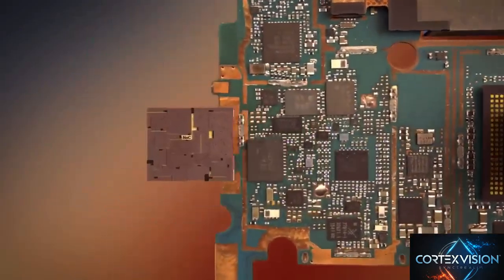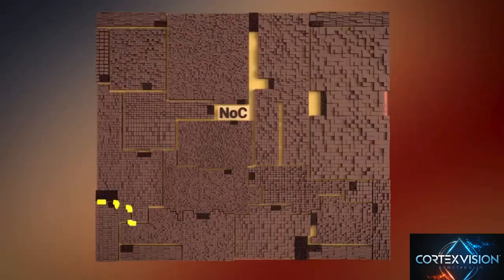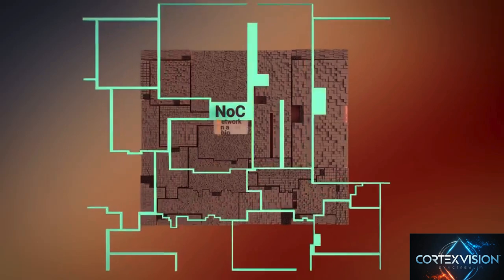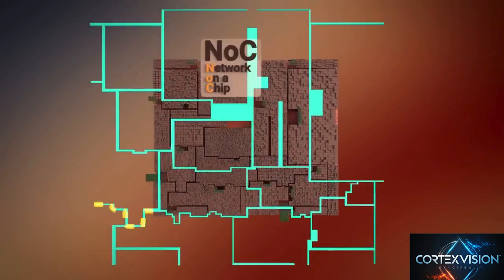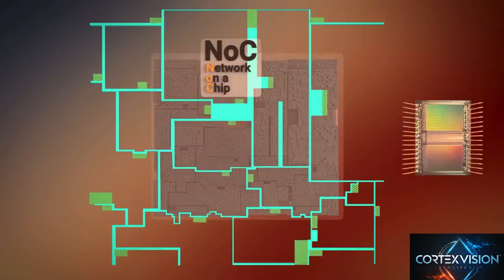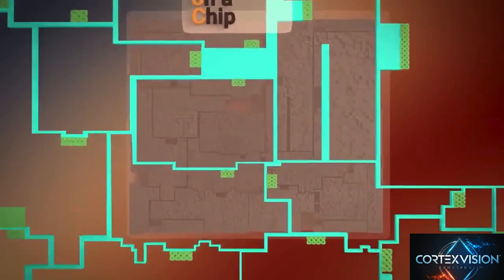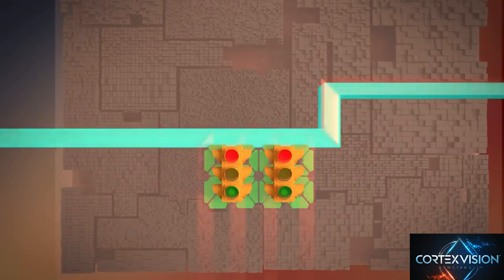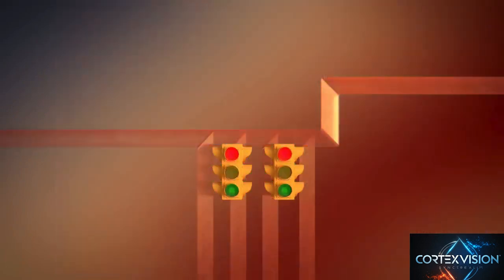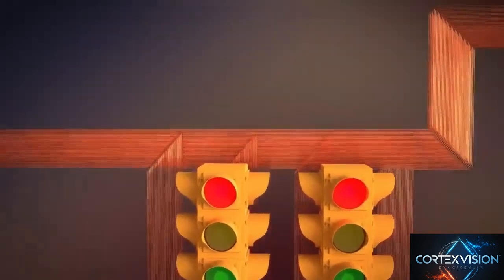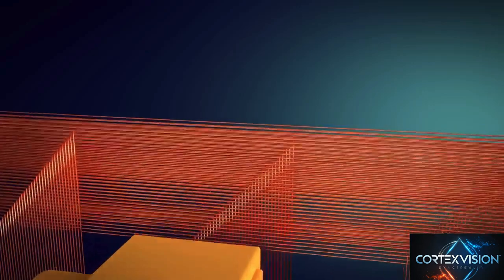One thing we've talked a lot about is the movement of data through the SoC. All of this data movement between the blocks runs over connecting wires on what is part of the network on a chip. This network has routers and switches for shared access to routes and targets like the DRAM. The routers and switches arbitrate the flow of data and act like digital traffic lights, and the pathways act as a digital highway. These highways have different widths of wires based on what they're talking to and the amount of information that needs to be sent.